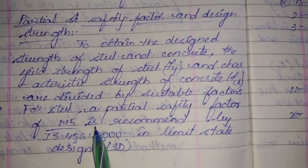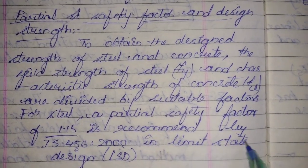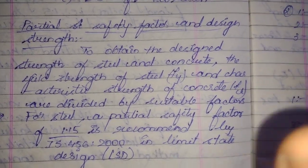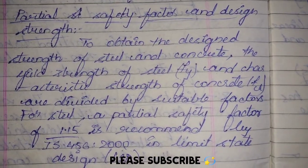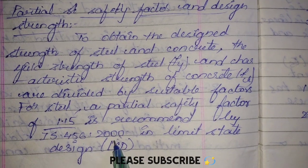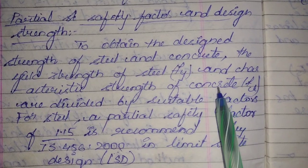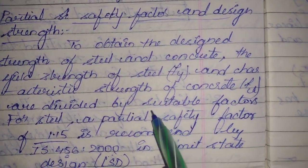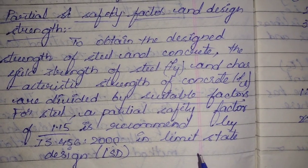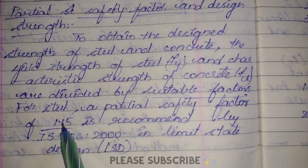For steel, a partial safety factor of 1.15 is recommended by the IS 456-2000 limit state design. So remember, this is as per the IS codal provisions, which are the data I am providing as per the IS code 456-2000. Okay, so here we are dividing this yield strength and characteristic strength of concrete with some suitable factors, we are calling that as partial safety factors. To get the design strength of materials, okay, to get the design strength of steel, we are dividing it with 1.15.